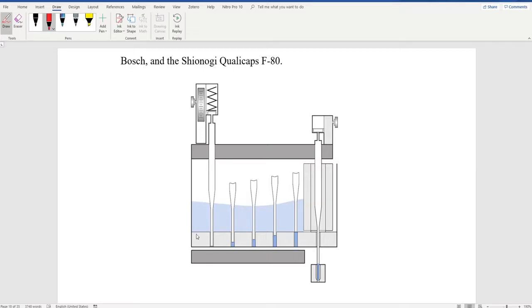What you see here is a disc containing accurately drilled holes. The disc has a thickness, as you can see, and the holes have a diameter that is in relation to the bodies of the capsules that I want to fill. This disc will be at the bottom of the rotating hopper, at the base of a rotating hopper. So when this one moves, the disc moves.